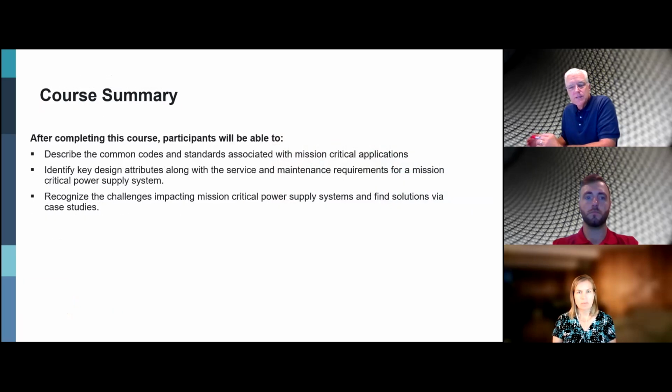So to recap the applications that we've shared, we had 3 unique standby applications serving healthcare needs and their requirements. Lake applied 2 fuel sources, diesel and natural gas. Diesel met the Type 10 expectation. Natural gas gave the hospital longevity and power supply with unlimited fuel. This project also brought cost advantages of natural gas and an alternative to peak shaving practices. Oregon State